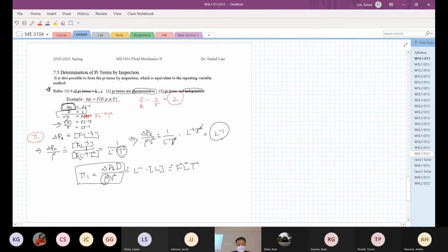You can find several pi terms, or combinations of pi terms. If one looks similar to a common dimensionless group, you can take whatever operator you want to tweak the shape and form of the pi terms to make it something nice, like a Reynolds number.